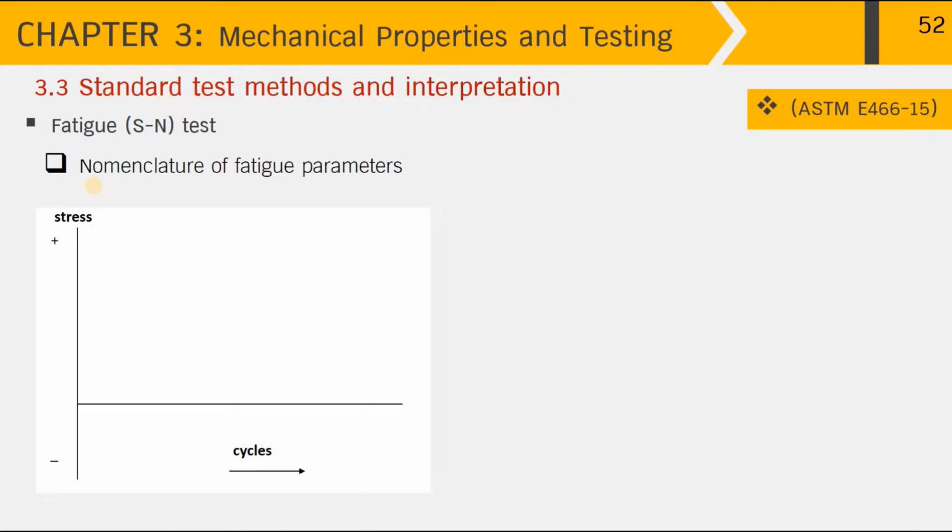And before we go into the determination of the fatigue performance, now I would like to introduce you the nomenclature of the fatigue parameters. As you can see from this graphical demonstration, we have here in the x-axis the time or cycles of fatigue, and along the y-axis here is the stress. And remember, the tensile stress is positive and the compressive stress is in negative values. Over here, I introduced you the fatigue cycle in the most simple form of the sine curve.